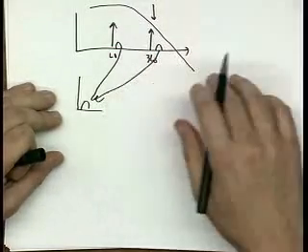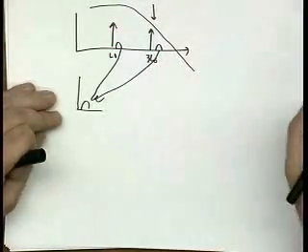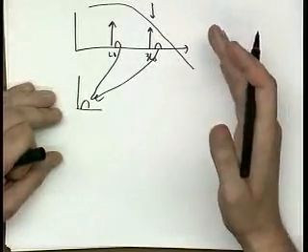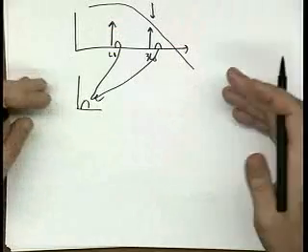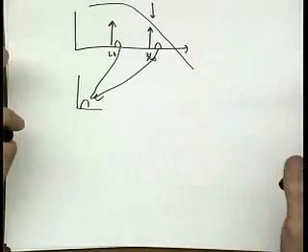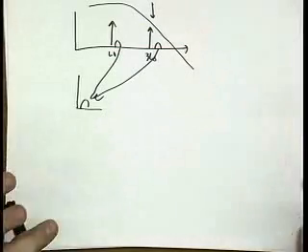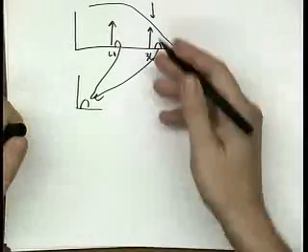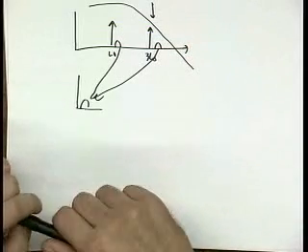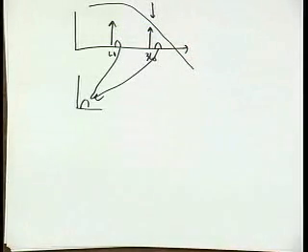So it's one of the reasons I could just go for the third and the fifth and be okay, because the third and the fifth are so close that they won't be hurt very much by a real pole. But by the time you get to the seventh, that's essentially a factor of hopefully like 49 suppression. That's a lot of suppression, even without any funny mixer tricks. But the third harmonic, you're not getting more than maybe a factor of 10, and not even that, really. So that's why it's worth bothering with.